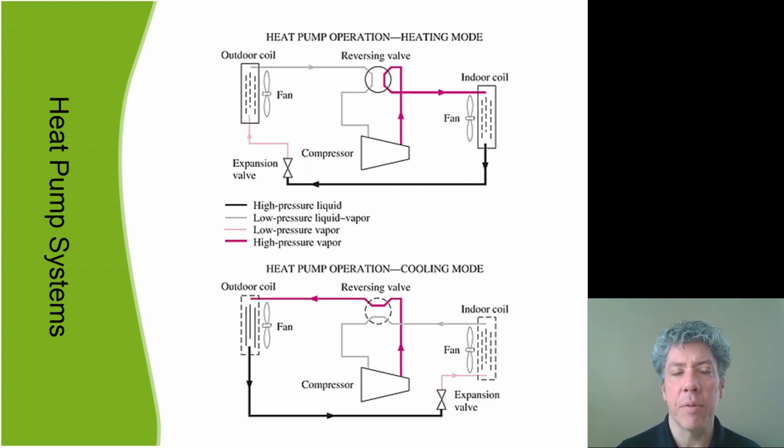and that's not very practical. But anyway, in a home, such as my home, a heat pump is actually not that much more expensive than an air conditioning system. And I highly recommend you look into one if you ever have to replace your air conditioner in your home, because a heat pump can save you a whole lot of money. When the temperature outside is mild, the heat pump can run and basically pull in 2, 3, 4 units of thermal energy for the price of 1 unit of electricity. And so that can end up being quite a bit cheaper than natural gas or propane.